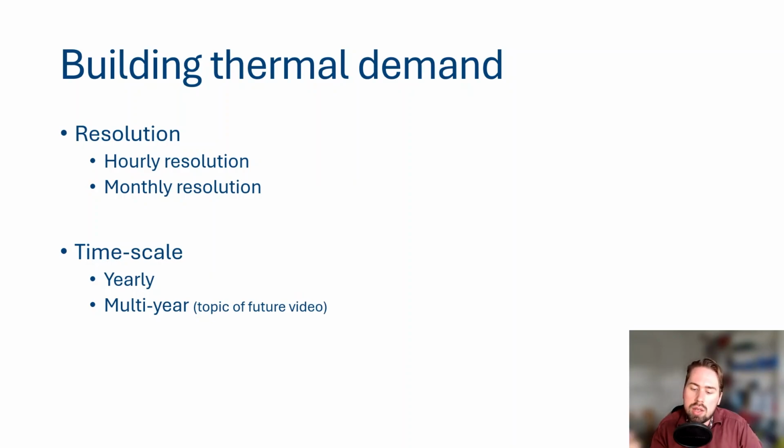timescale. Now, if you have, for example, a project that will be built in multiple phases, for example, apartment buildings on a collective system, you can end up with a situation where your thermal demand changes over time. And then you can input the load data, both hourly and monthly, on a multi-year timescale. But this is a topic for a future video. So today we will assume that you calculate or you come up with a load profile for your building and that it repeats over the whole simulation period. Now let's discuss both this hourly and monthly resolution.